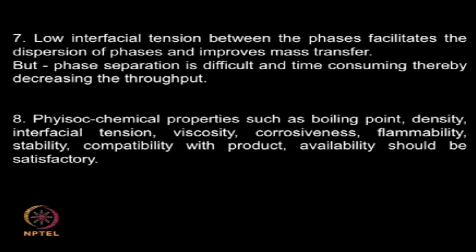For example, it should not be corrosive to the material of construction of your extractor, it should not be flammable, that means you should not use solvents which are highly flammable or have very low boiling point, because a lot of solvent will vaporize during your handling and you will be losing solvent as a vapor, and also you will be having possible explosion hazard or flammable hazard if the solvent goes into vapor phase.